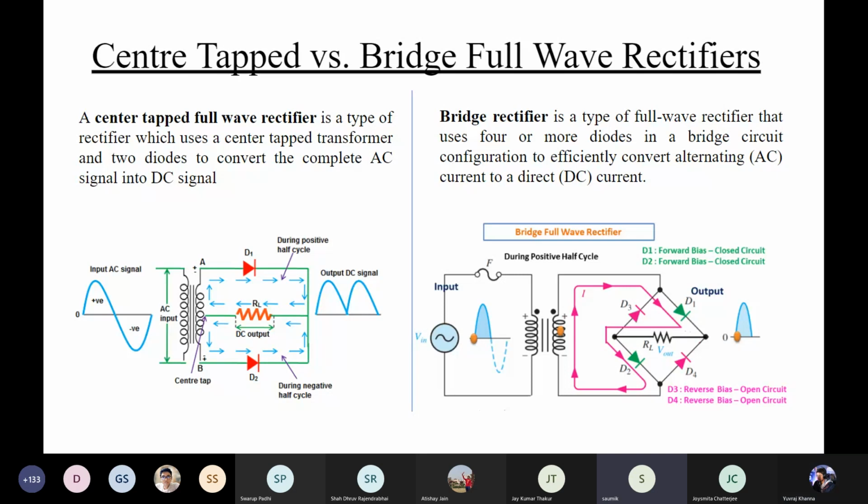This is the same transformer. You have the center tap or you don't have the center tap; otherwise, how will you compare? When you are not using the center tap, you have one kind of circuit, and the number of coils for these two transformers is the same. If you change the number of turns in that coil, you cannot compare these two circuits. So the effective VA rating for the transformer in the center tap case will change because you are using half the number of turns.